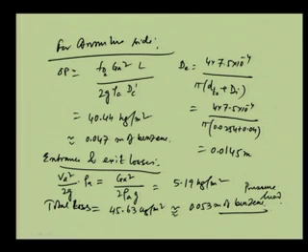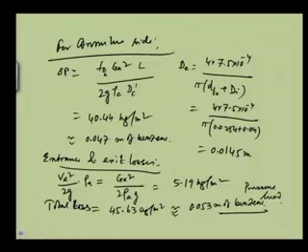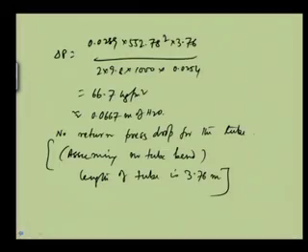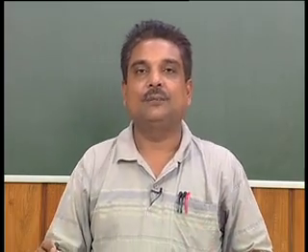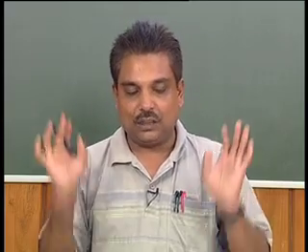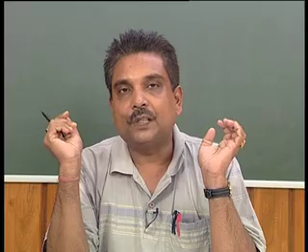Okay. So, the pressure drop on the annular side we have calculated based on the frictional loss and the entry or exit losses. And in the case of the tube side, we have calculated only the frictional losses. This way we can find out the pressure drops and see whether they lie within our allowable limit or not. So, this is all for today, and in the next lecture we are going to discuss shell and tube heat exchanger calculations. Thank you very much.